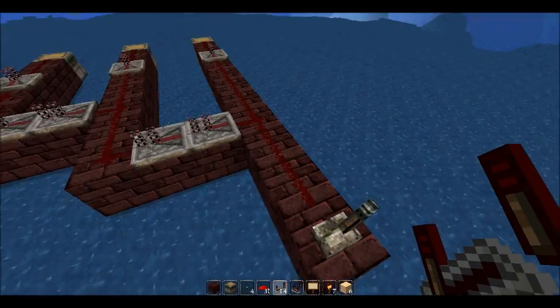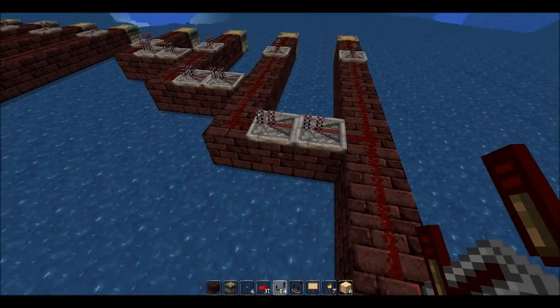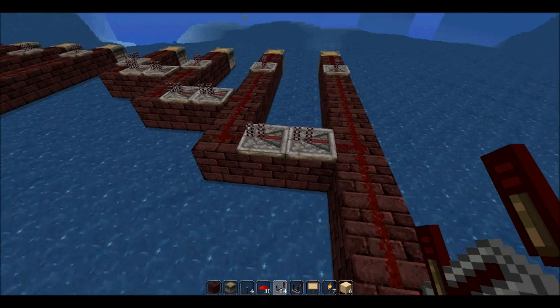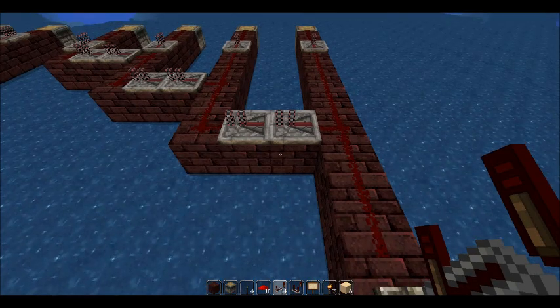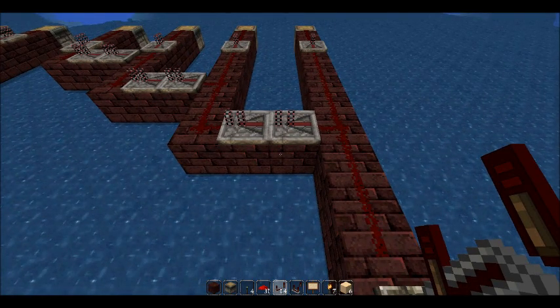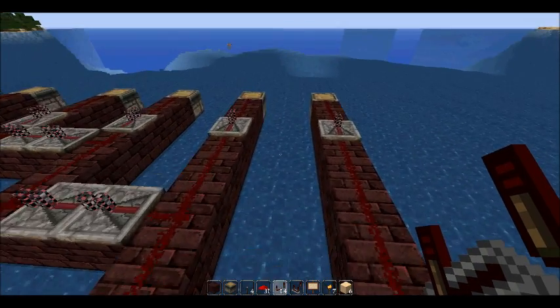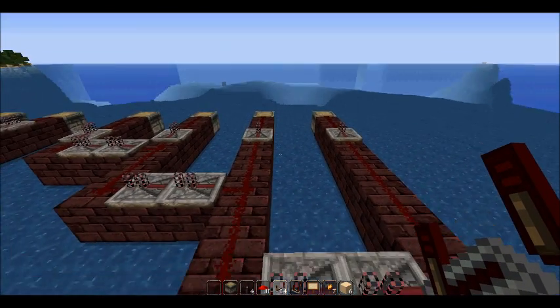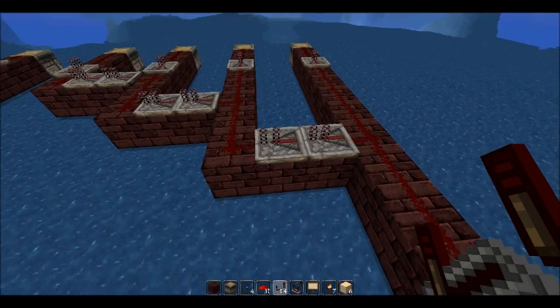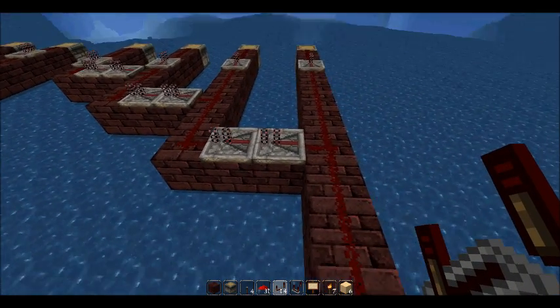And now we come to one of the really important points of all this circuitry: if you want a delay, if you want one thing to happen after another, it needs to be 0.2 seconds afterwards to allow for the actual function to happen. So let's say the piston takes 0.1 seconds to go up. That takes up one of these, so you need another one.